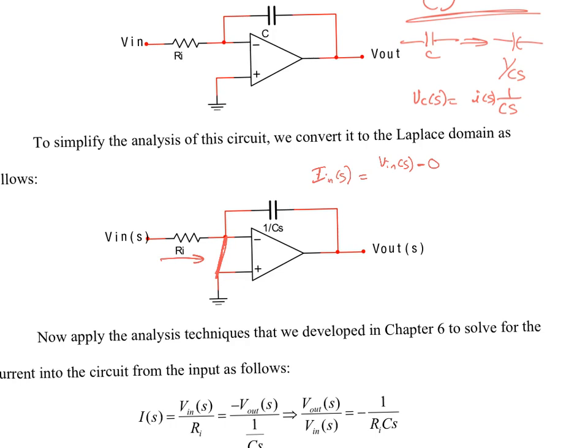But there isn't actually a short circuit because all the current would be going that way, right? So this is not a real short circuit. This is a virtual connection. It doesn't really exist. It's just a virtual connection. And the idea is that current can't flow there, but it helps give you a sense of what the voltage needs to be. Okay? So we show it as a virtual connection, but it's not really there, and that just helps us tell what the voltage is at that point.